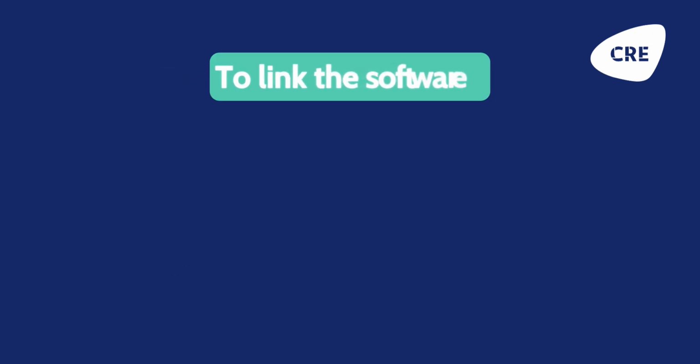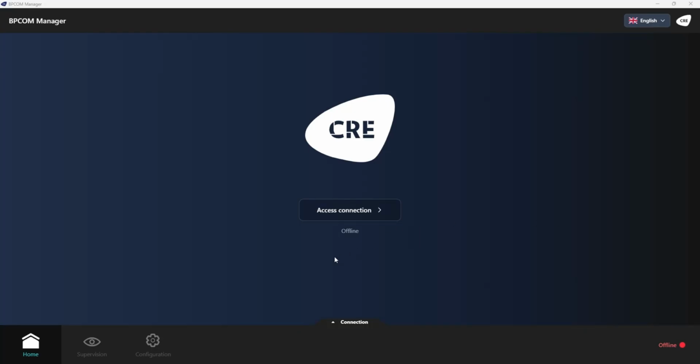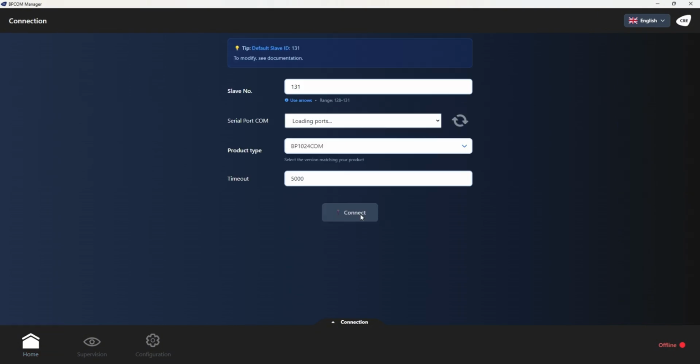To link the software to the charger, the connection between the PC and the product is made through a USB to RS485 converter. This converter is sold separately. When you launch BPCOM Manager, you arrive on the home page. To establish communication with the charger, click Access Connection.